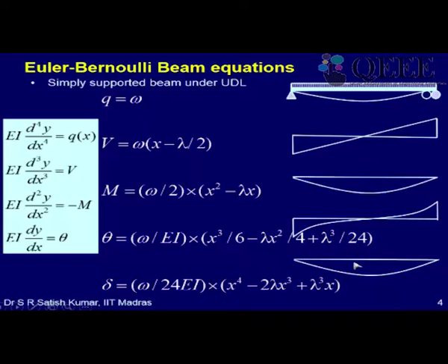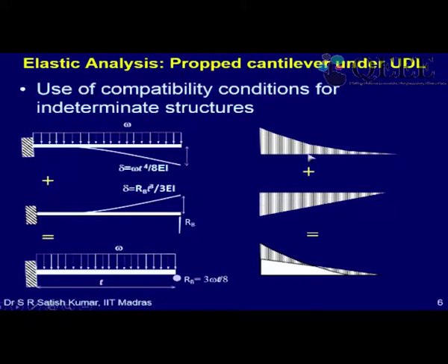So that is how we should understand that the two properties affect the deflection and the slope of the beam. Okay, so for using the compatibility condition, we must know the material constitutive relation, and as such the equilibrium equation, the compatibility conditions, and the material constitutive relation, in this case stress proportional to E into epsilon, strain.